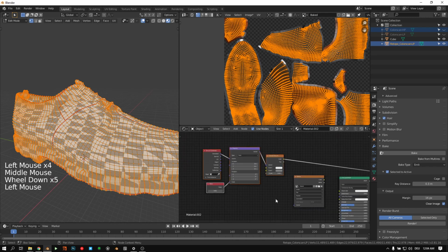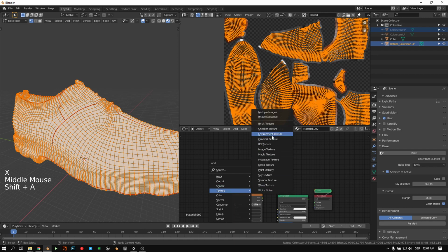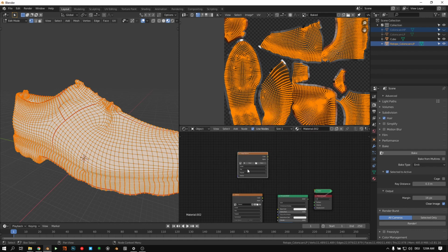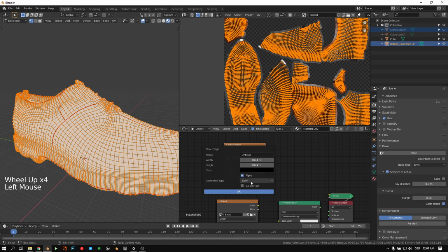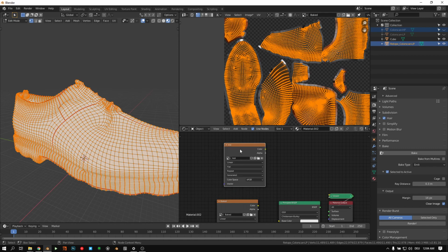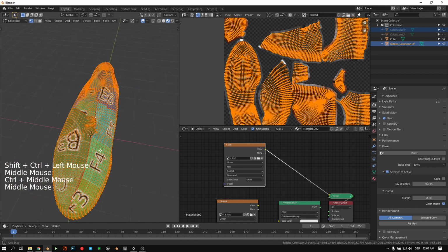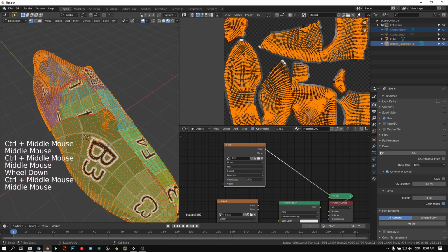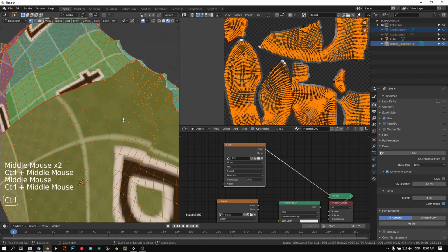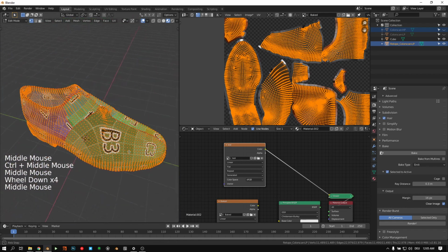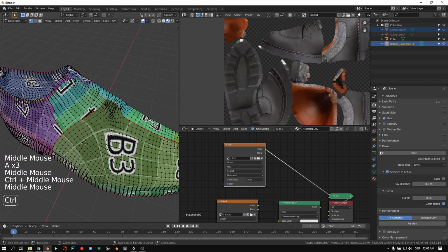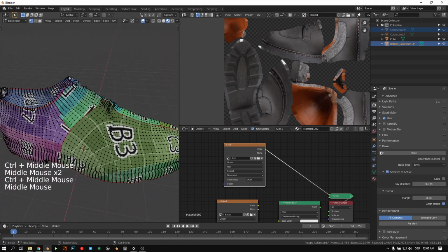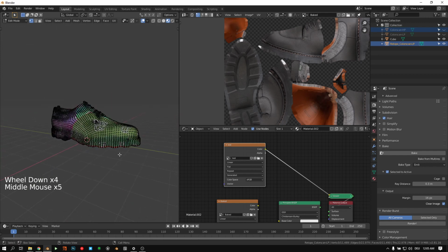So this is one way, or you can create a new texture, a new image texture, create new, and instead of having blank, use a color grid, for example. Name it test, for example. Click OK. And now you could check your rescaling before unwrapping and before baking, of course. Right. So as you can see here, this is pretty horrible. So I would suggest fixing that before baking anything.